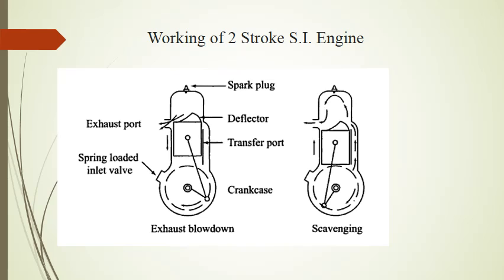The charge is sucked through spring-loaded inlet valve when the pressure in the crankcase reduces due to upward motion of the piston during compression stroke. After the compression, ignition and expansion take place in the usual way. During the expansion stroke, the air in the crankcase is compressed.